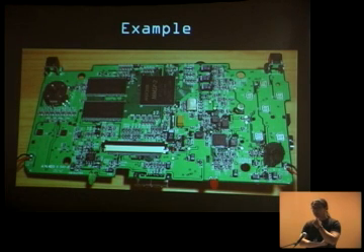The smart cards themselves have gotten very sophisticated. They start putting layers of metal on top, so if you open them up, you can't read them. They have what we call alarms on the chip, so if you reduce the VDD or glitch the clock, it sets an alarm and the chip shuts itself down. They're very paranoid when they build these, because those are meant to be tamper-resistant modules, like chips. But they haven't really seen tamper-resistance at the board level yet. So the smart card modules are pretty well engineered. If you get the right one, you have to know what they're doing inside. They're pretty good. So, any other questions?